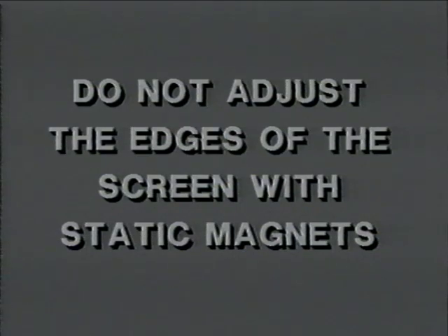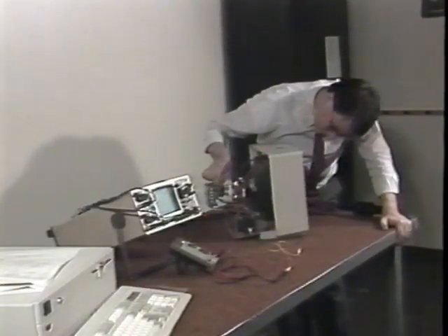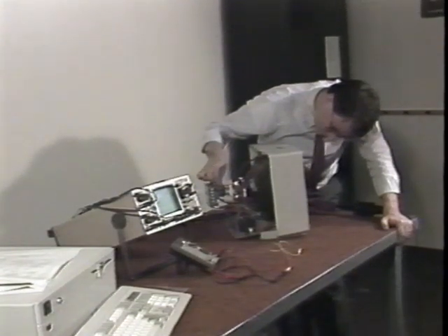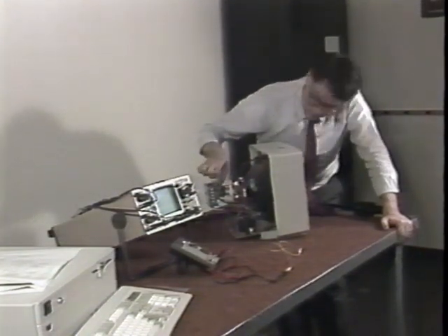If there is a green border on the center lines, use the 6-pole magnets to correct it. Move the individual tabs to remove vertical green lines, and move the 2 tabs together to be rid of green horizontal lines. Do not attempt to adjust the lines or dots near the edges of the screen using this procedure. Static convergence is effective only at the center of the screen. Once the area in the middle of the display is converged, move on to the dynamic convergence adjustments.